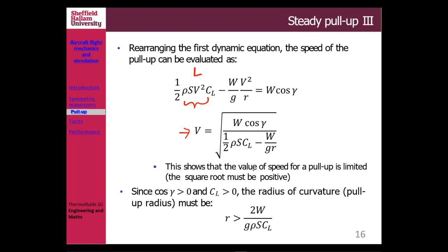Then in these equations, if you rearrange, you can know exactly what R, the radius of the turn or pull-up, you need in order to keep the load factor acceptable. So remember, the smaller R, the bigger load factor, right, from the previous equation.